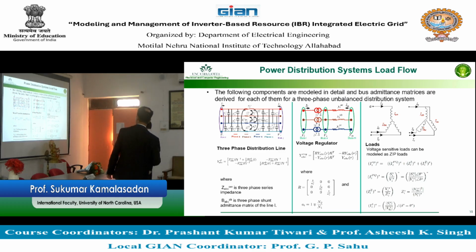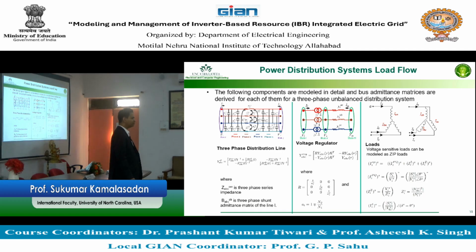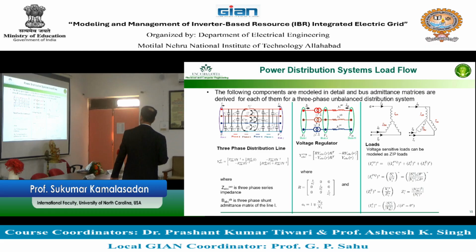So having said that, A, B, C and neutral, all these lines, three-phase, four-wire or three-wire? Everybody knows three-phase, three-wire, three-phase, four-wire. You will need to have this. So you got to represent them in the form of impedance plus the capacitance on diagonal element and cross diagonal element representation of the series representation of this three-phase impedance.